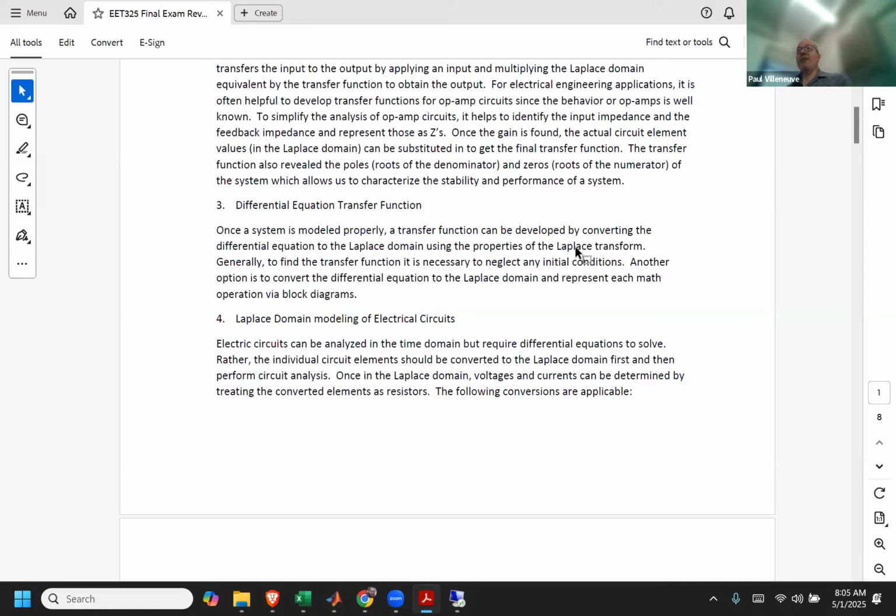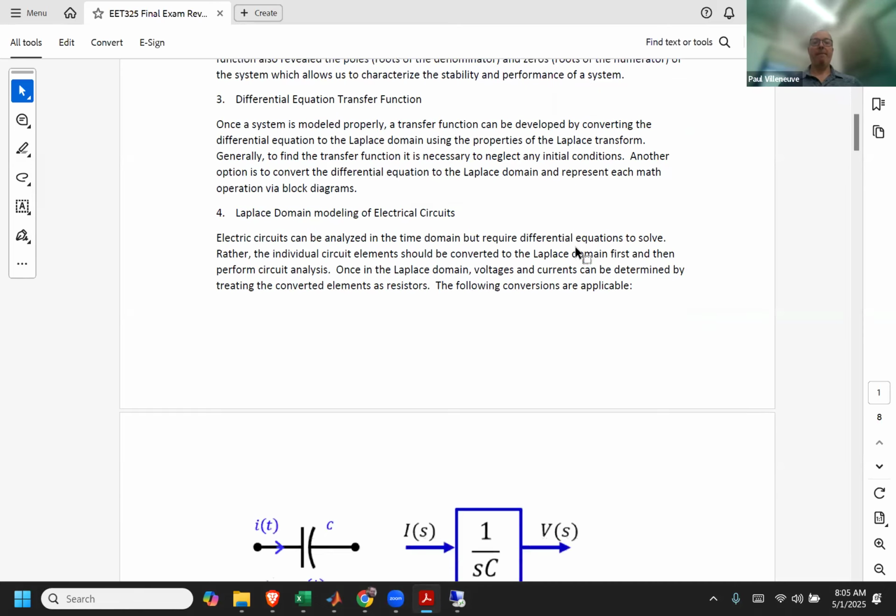And so sometimes block diagrams are better because if you're trying to represent a physical system, you can actually break that physical system up into smaller parts, which correspond to the blocks. So if something is not coming out the way you expect it, you can actually model those individual points and compare those to each point on a block diagram. And hey, there's a problem between this point and this point. So it really helps with troubleshooting.